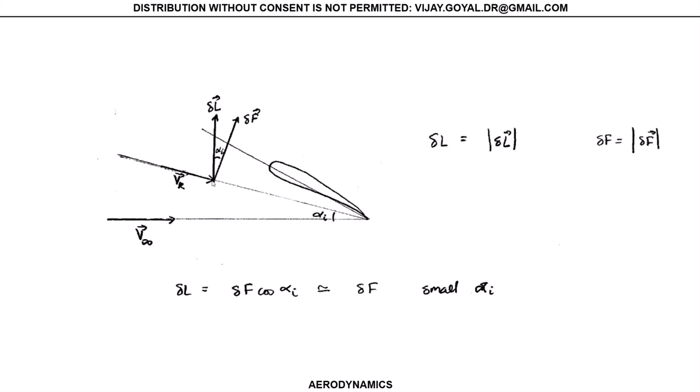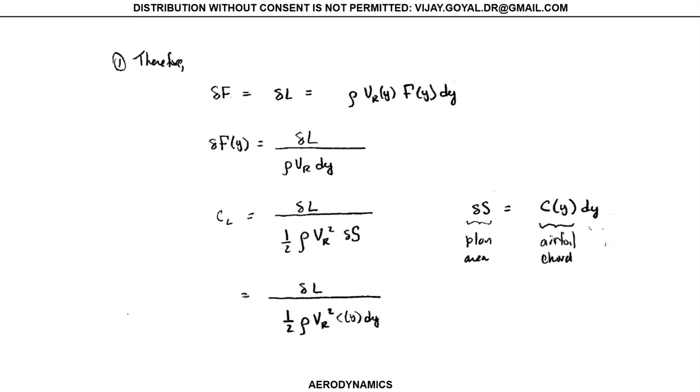So in this location right here, you're going to have an extra component there. That's where that component comes from. And this is equal to this. And typically your induced angle is very, very small. So therefore this is equal to this. You can say these are very close to each other. That's a very good approximation. There are cases in which you may want to calculate that exactly.